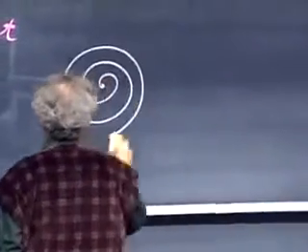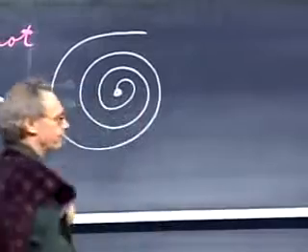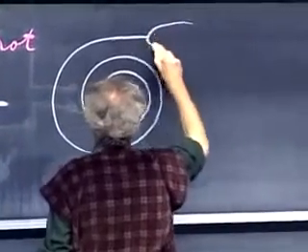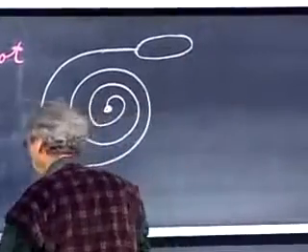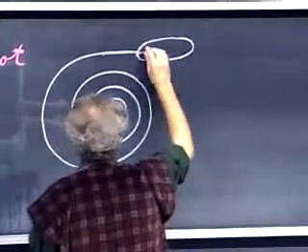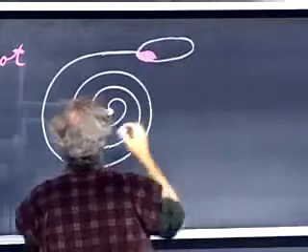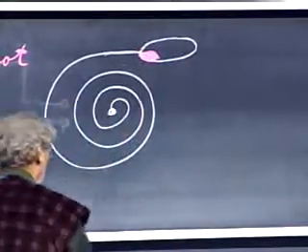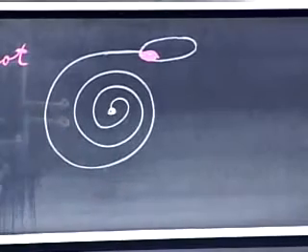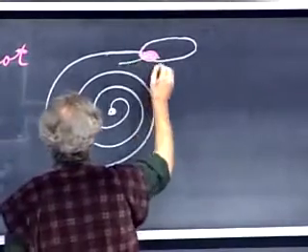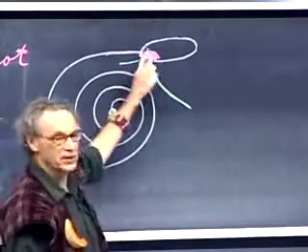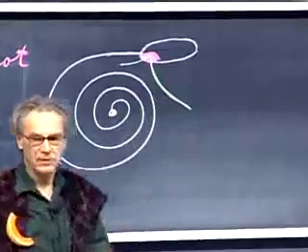So the coil is like this. Bimetal. And at the end here is a glass container, and there is some mercury. And the mercury is here on this side, because notice the way I have tilted it a little. The mercury rolls to the left. And there are here 2 wires, electric wires, one here and one here, which go to the heating system. And so when the mercury is here, which has a good conductivity, the heater is on.